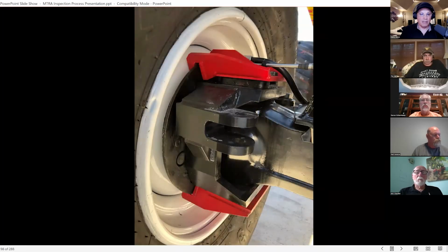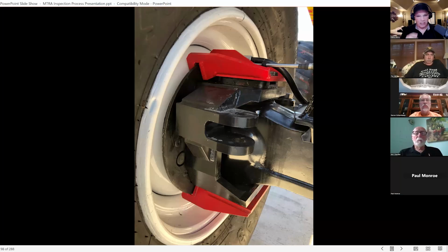See, in a ZF style, where again there's not a lot of room to be able to do a full ring, you can, but it's pretty space efficient and very constrained. So we allow them to be separate pieces like this, but you need to have a strap that ties them together, even if it's just one vertical piece on each side of the bracket that ties the upper and lower together.